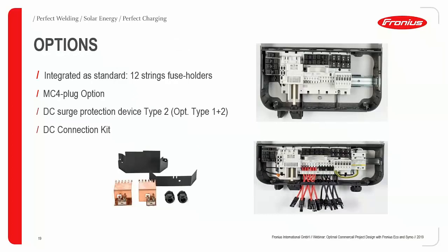The Eco inverter is a single tracking unit, and it has 6 string dual pole fusing. That means a total of 12 fuse holders. The inverter itself comes without fuses, only with bolts, so you can plug in the correct fuse according to the panel that you are using.